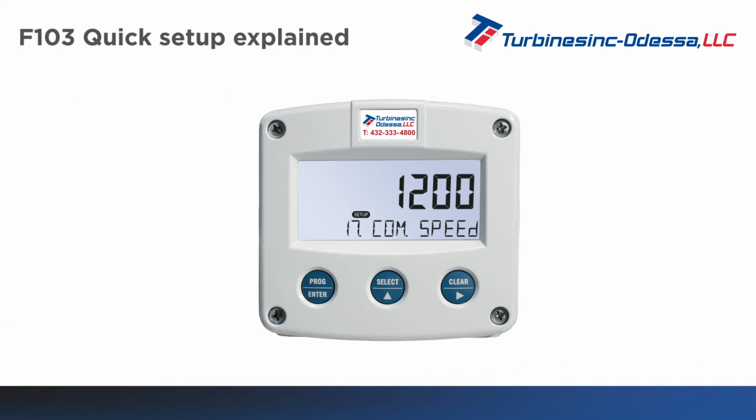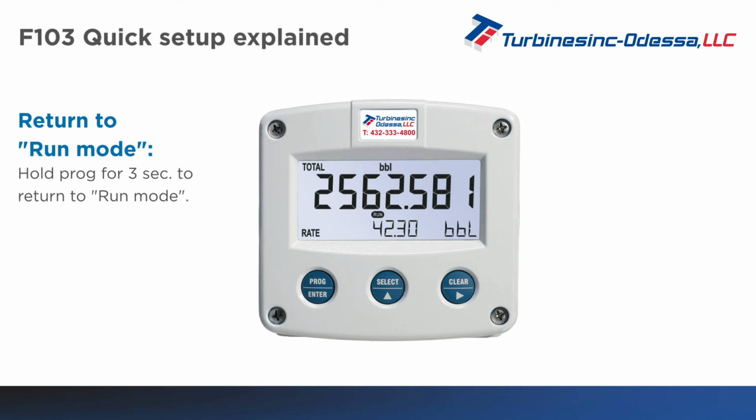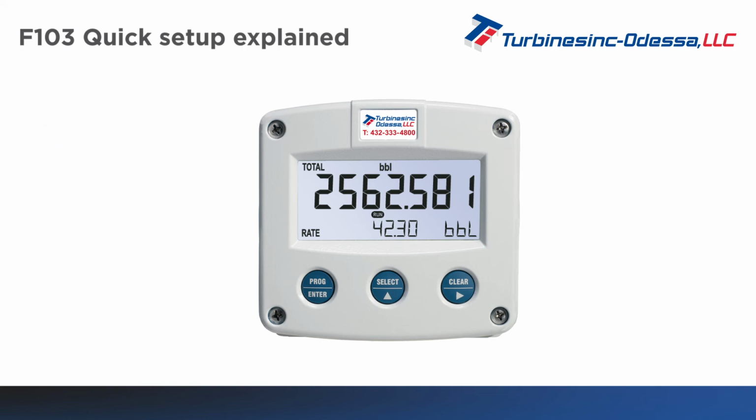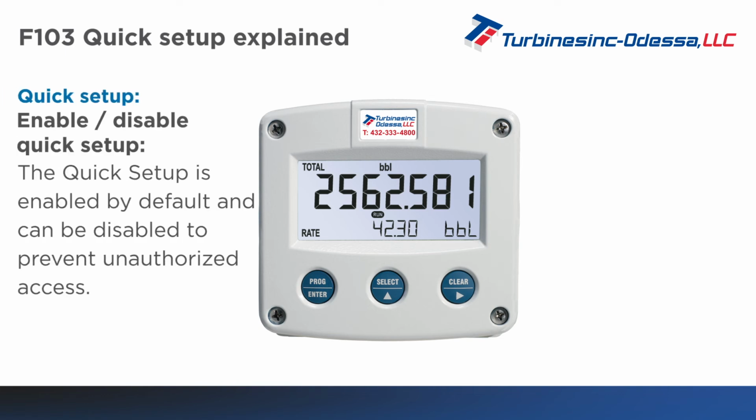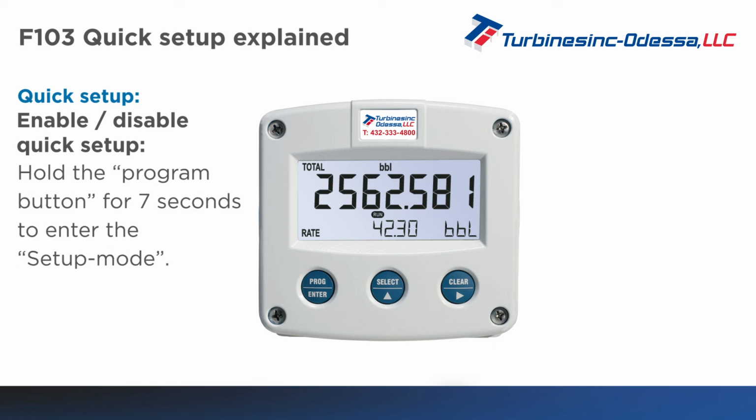To leave the Quick Setup menu, return to the welcome screen and press the Clear key. Or you can press Prog for 3 seconds and return to Operator mode. The Quick Setup is enabled by default and can be disabled to prevent unauthorized access. To disable the Quick Setup, hold the Program button for 7 seconds to enter the Setup mode.